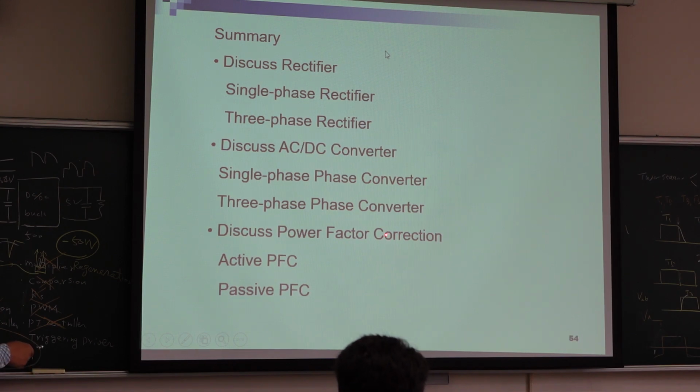Then power factor has another definition. It is cosine theta multiplied by the distortion factor. So you have to redesign the power factor correction. You cannot use only a capacitor, because the capacitor value cannot change. The load is always changing. If you use a fixed capacitor, how can you obtain very good power factor at different loads? It is impossible, right? Because your load is always changing.